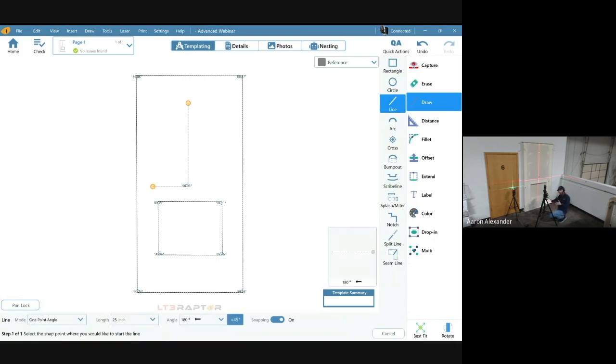So now the angle we're drawing this line is in relation to the line we rotated to. So since we rotated to plumb, whatever angle we draw this line at, whether straight up, straight down, left or right horizontally, it's going to be plumb in space here. So I'm going to switch to my miter color. And I'm actually going to just click in the little screen here on the right and spin that line around till it's going straight up.